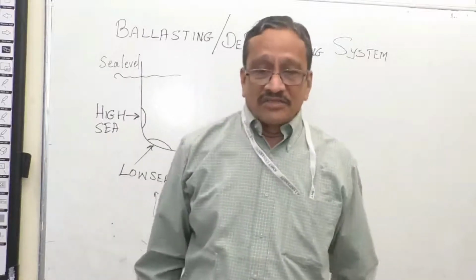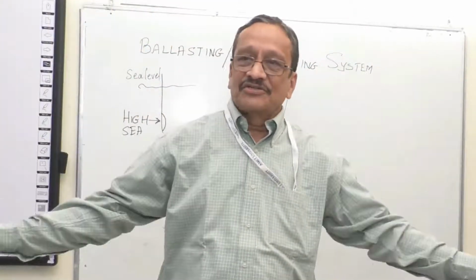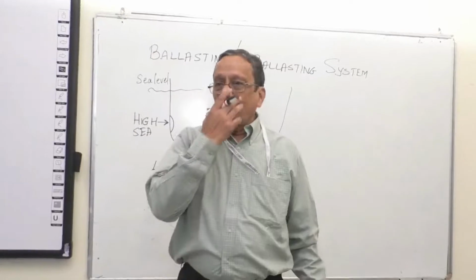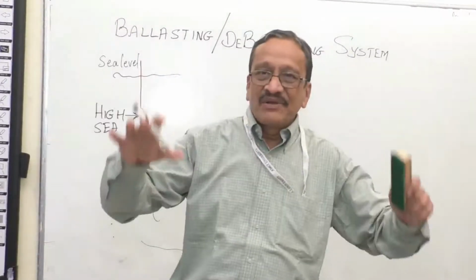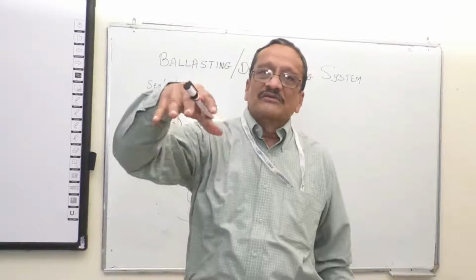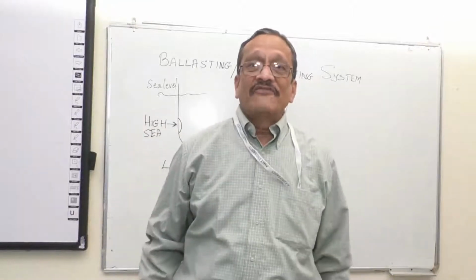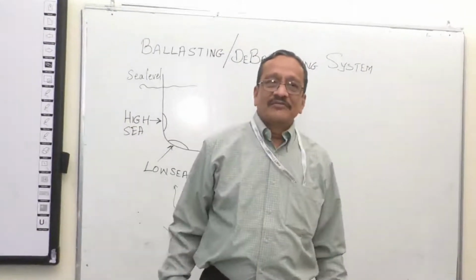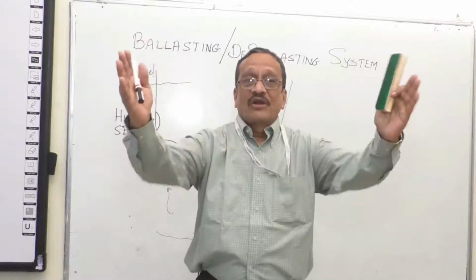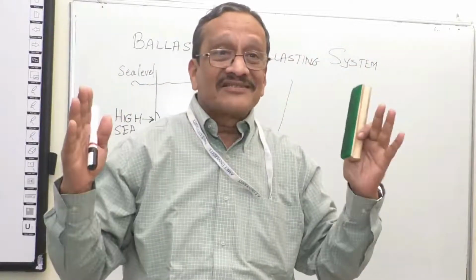So here you are going to ballast the ship. When do you think you are going to ballast the ship? When the ship's cargo is being discharged. When the cargo is being discharged, you are going to ballast the tanks. Right? Why is that so? You are going to bring about stability of the ship. Now what do you understand by that? You are going to fill up the water so that the frames of the ship are not affected, which is very, very important. Please mind. The frames are your backbone on which your hull is built. So we don't want any of those frames to be affected with stress and strain.